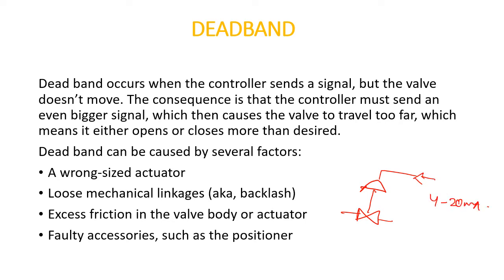At 4 milliamperes the control valve is supposed to be fully closed, 0%, and at 20 milliamperes it's supposed to be 100% open. Now suppose you have sent a signal of 4.1 milliampere and the control valve still has not started to move. So there is a deadband of like 0.1 milliampere present there.